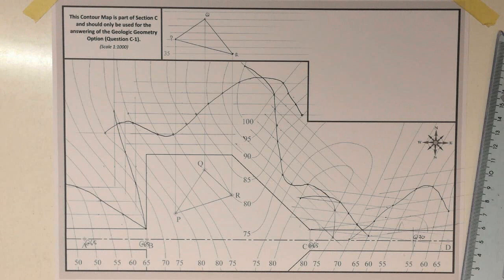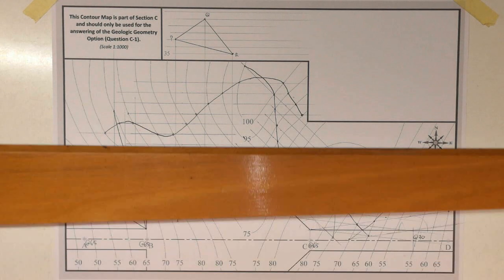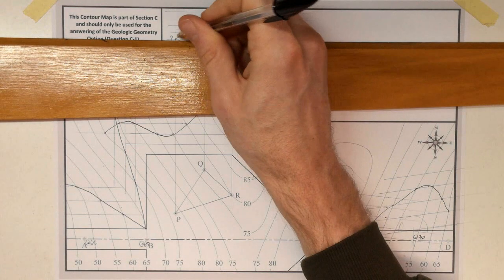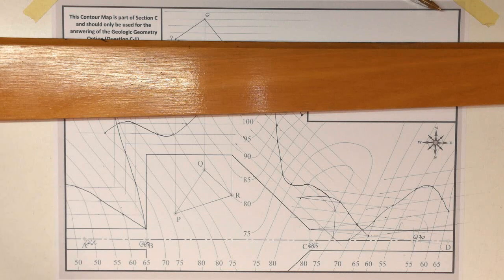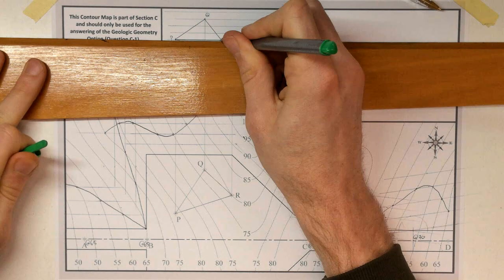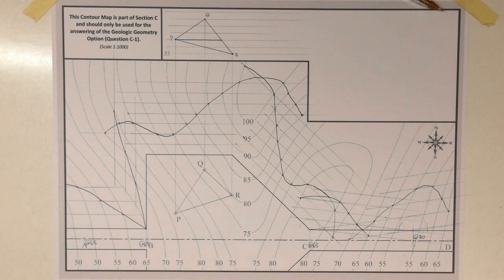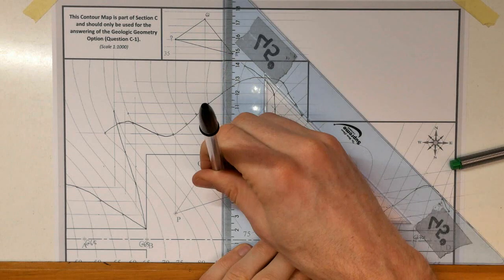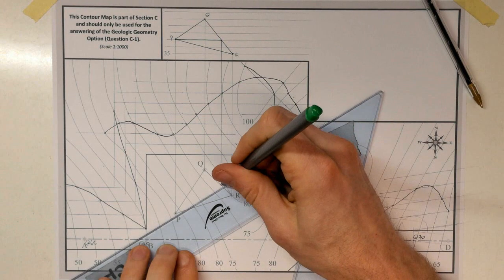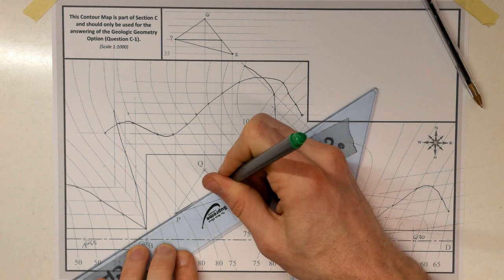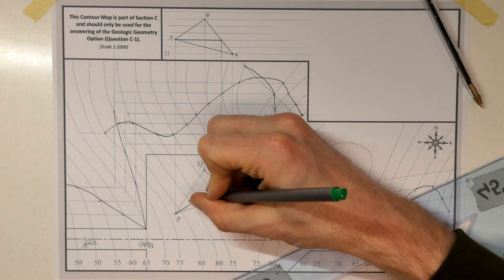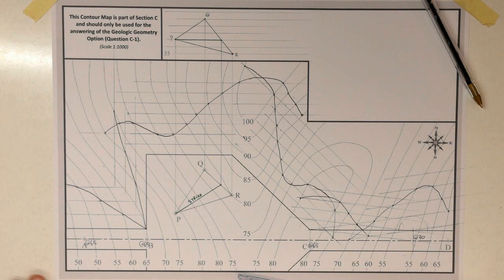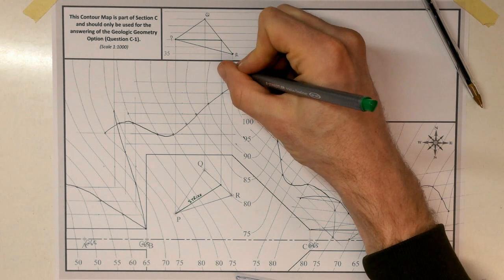So for the strike, I'm going to draw a level line. Let's take a level line here. Should use that green colour here. So my level line, project that down. Okay, so that is the strike. S-T-R-I-K-E. It's a true length line. Should have projected it down there.